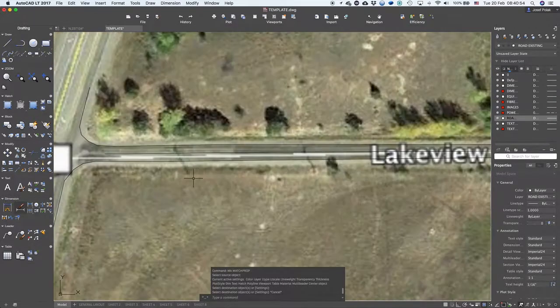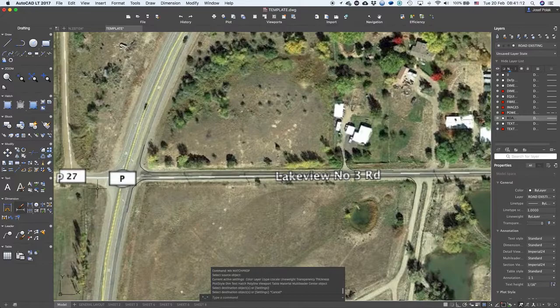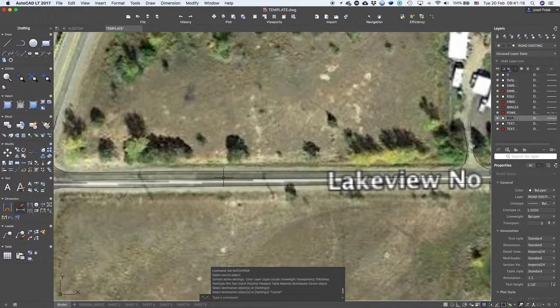Now for the country roads, every road, doesn't matter which one is it, has a right of way. Country roads in general have a right of way 30 feet from the center line. Highways might be different. That's why for highways, which is this for example, we don't show the right of way. For any other small roads, we show the right of way.